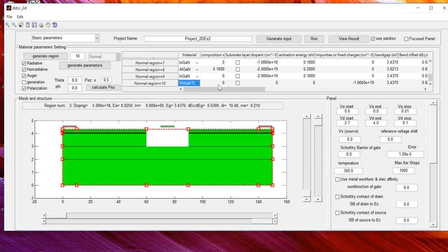I just make the contact perfect. If you simply put additional material by yourself, gallium nitride has polarization charge, another material doesn't have polarization. You make a bending in the contact, and that could cause some trouble.